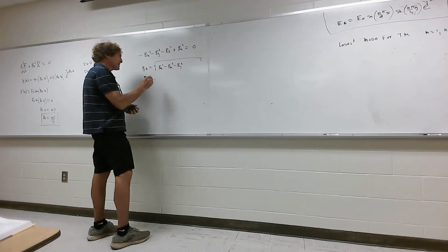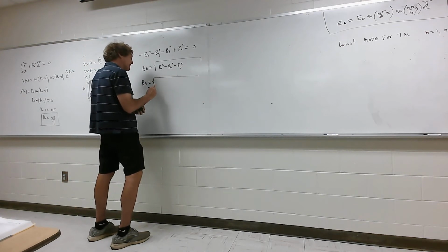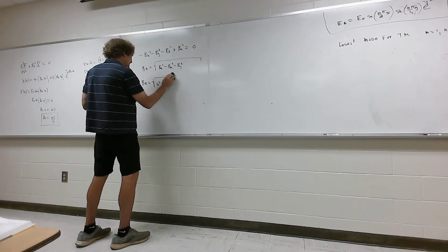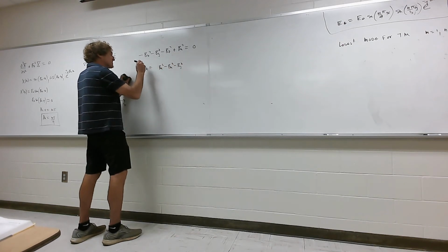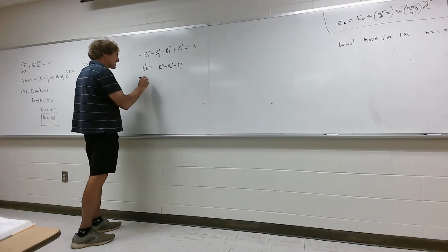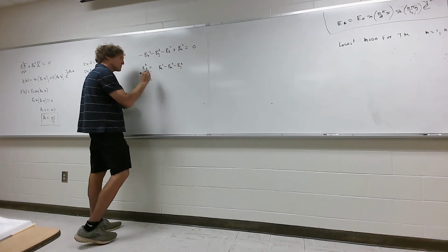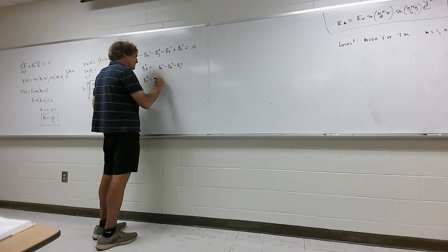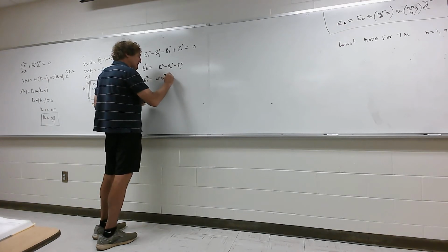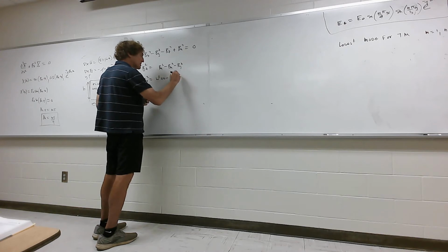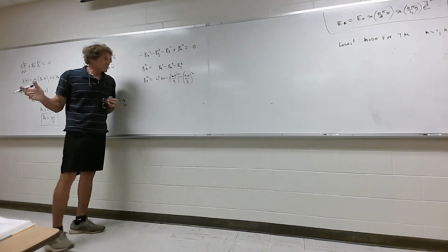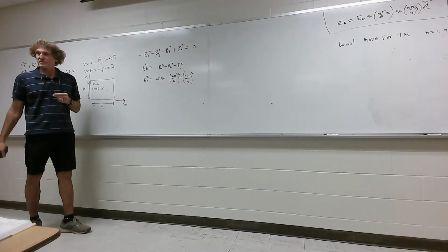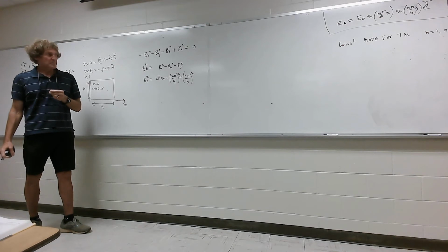Alright, come down here, and that becomes square root omega squared. Tell you what, I'm not even going to do that. I'll make it easier on both of us. I'm going to leave it as that. And I'll say beta z squared is equal to omega squared mu epsilon minus m pi over a squared minus n pi over b squared. The only thing I'm doing, I'm saving myself some time on this one. Y'all follow me? I just put the variables in there.